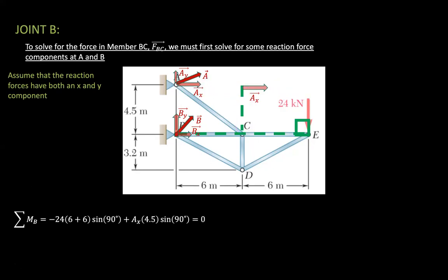The sum of the moments must be equal to 0 because this whole structure isn't turning. So it's in static equilibrium. For static equilibrium, we must have that the sum of the moments is equal to 0 and that the sum of the forces is equal to 0.